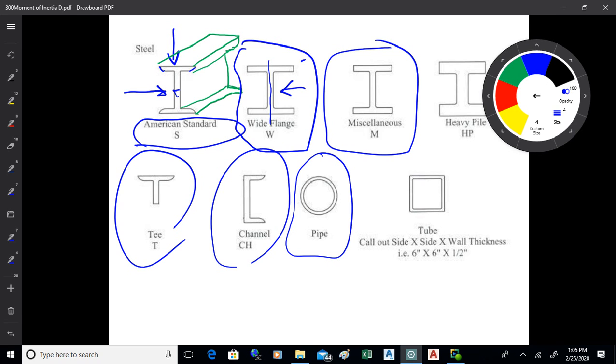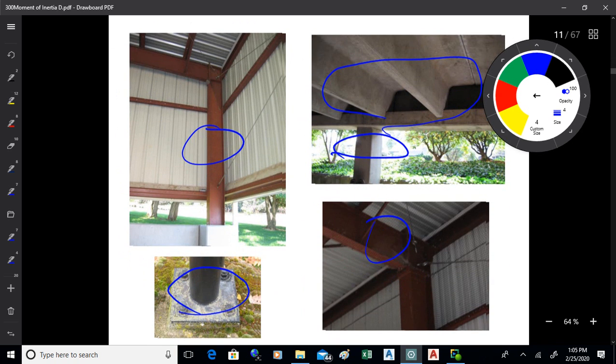They all have high moments of inertia and use the material efficiently. So you want a high moment of inertia for a low amount of material. Less material gets you less cost and less weight. So there are some common structural shapes used in different applications. There you see I-beams, double T's, tubes, things like that.